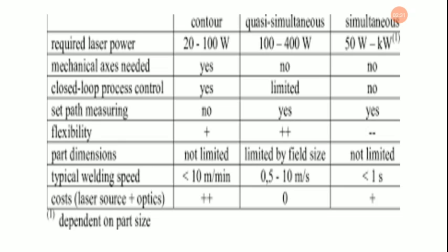So, a multi-characteristics response optimization model based on Taguchi and utility concept is used to optimize GTAW process parameters such as peak current, base current, frequency, pulse on time, gas flow rate, and welding speed on multiple performance characteristics, namely weld pool geometry, and characteristics such as penetration, face width, and back width.